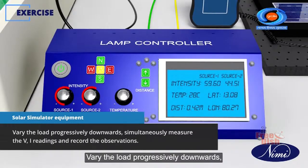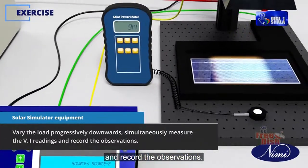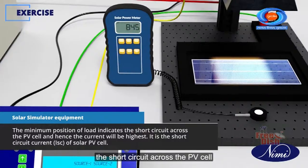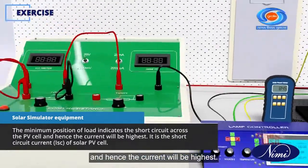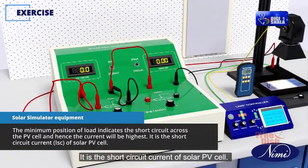Vary the load progressively downwards. Simultaneously measure the VI readings and record the observations. The minimum position of load indicates the short circuit across the PV cell, and hence the current will be highest. It is the short circuit current of the solar PV cell.